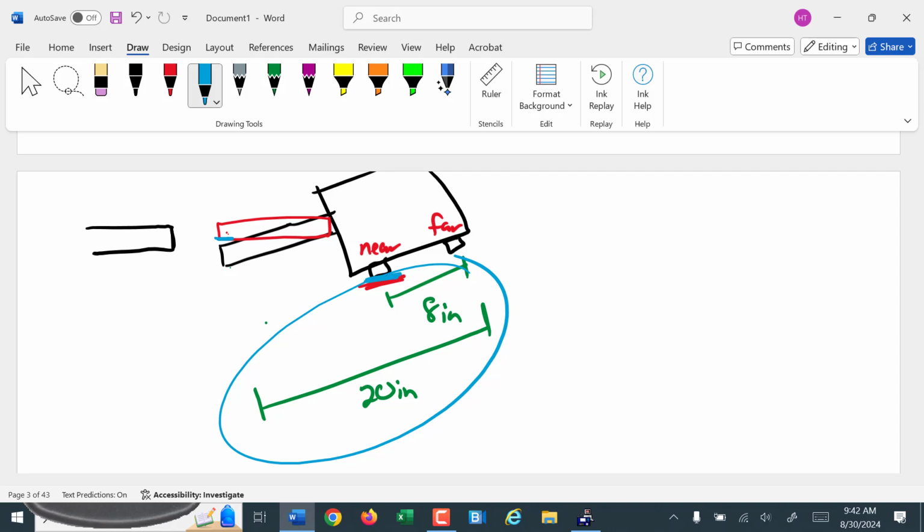The ratio between the shim and how far that shaft moves is going to be equivalent to this ratio of lengths. So if I shim that foot 0.010 of an inch, it is working on an 8-inch, called a moment arm, an 8-inch arm to that far foot.